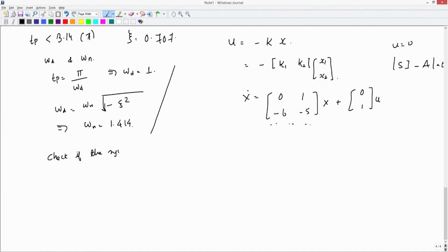if the system is controllable. This means just quickly find the rank of B and AB, and this should definitely be equal to 2, and you can easily find out that the system is controllable. Also, it is easier to check because it is exactly in the controllable canonical form. Okay. So, let us try solving this problem, right.